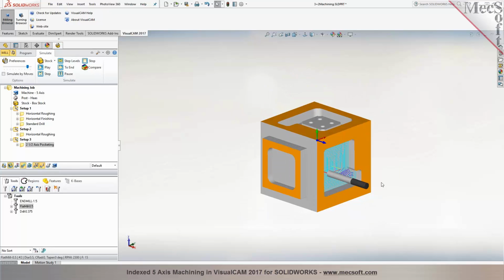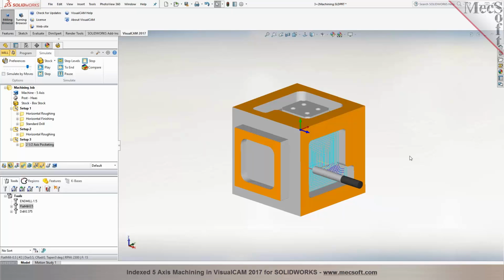Just one question, my friend, just there in that point. That step works because the last surface that you selected is flat and also parallel to the external surface. But if it's not flat or is not parallel, it works in the same way? Well, you need to have a planar surface if you want to use that for orienting your coordinate system. Now, if you have a sculpted surface, then you can rotate it by an angle, maybe like 45 degrees, so that the tool will be able to machine those features and there aren't any undercuts by looking from that orientation.